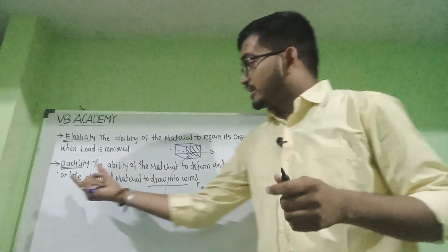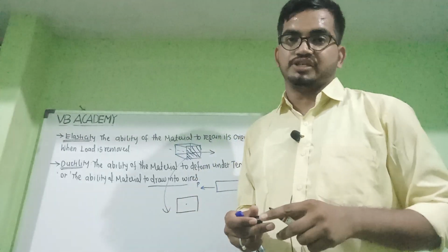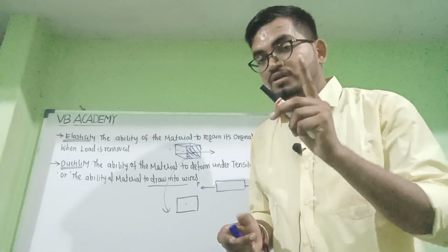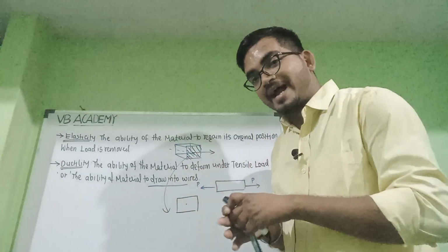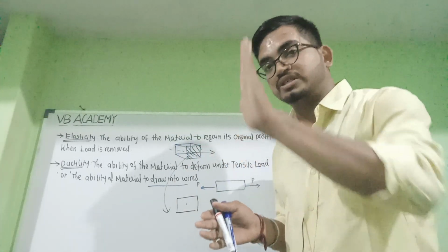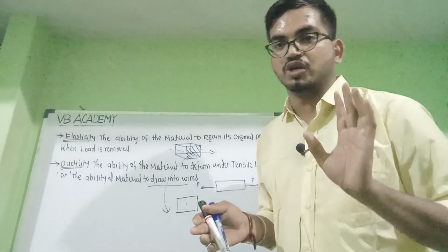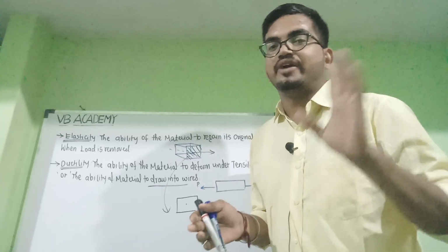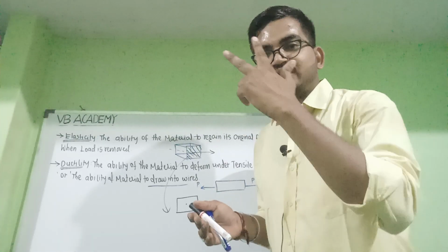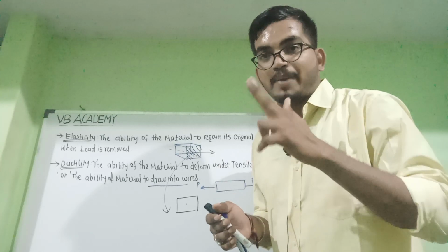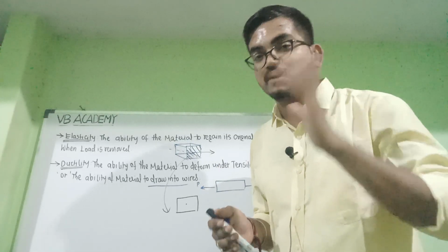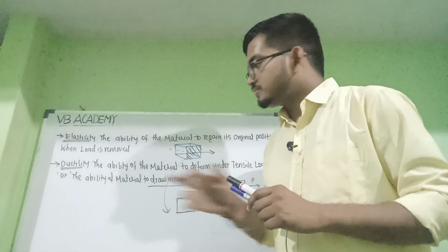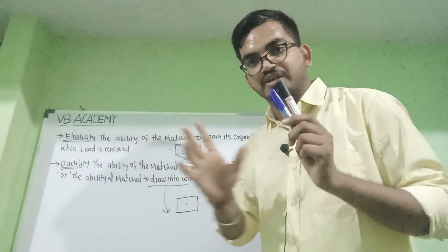easily. These type of ductile materials are weak in the shear. What is meant by shearing force here? If the load is acting parallel to the area of cross section, then the load is known as shearing load, which causes the body to be divided into two parts if you apply the shear force. Clear? Parallel force acting along the area of cross section. This is the area under shear, we call it. This type of ductile material is very weak in the shear.